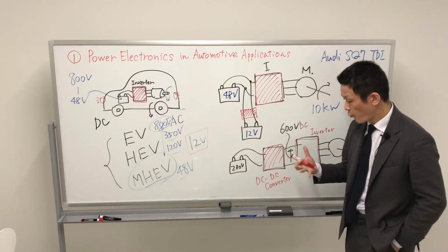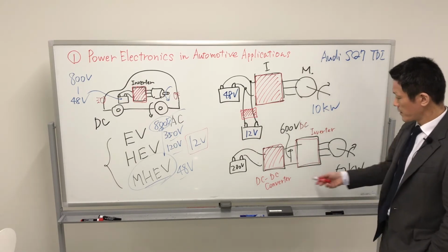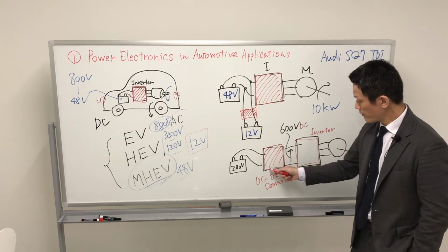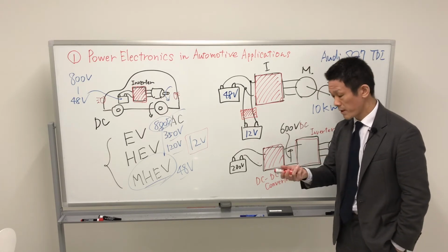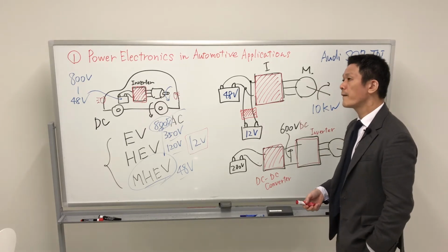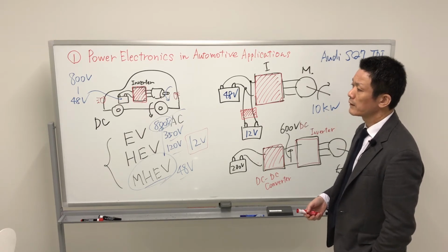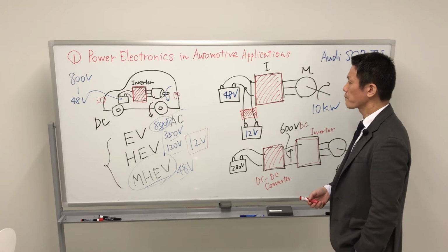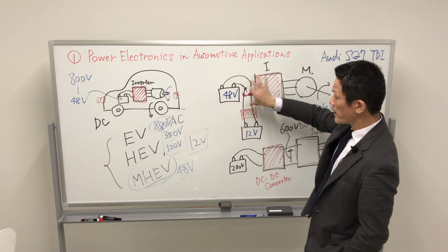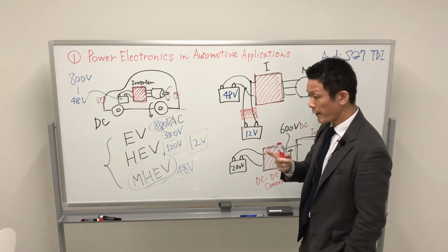In the case of the Toyota Prius, Yaris, and some Corollas, they have these original components, plus an additional DC-DC converter, which we call the boost chopper. And Volkswagen, Audi, Porsche, and Mercedes each have only the battery, inverter, and motor, very simple. But we require an additional power electronic system.